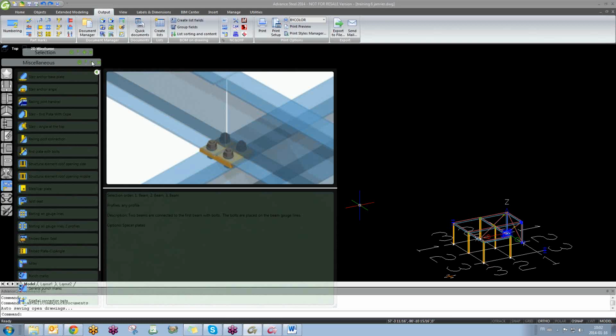So then I can use that command where you showed us about the concrete commands. I can use that for like concrete columns. So Hansa, what's the best way of doing this? I'm working on a job right now where the whole first floor is steel, but everything is framed into concrete columns. There's no steel columns. Everything's concrete. And at each concrete column there's a bearing plate on top of that column. So would you use that plate command and just create the plate, or would you use a member there too?